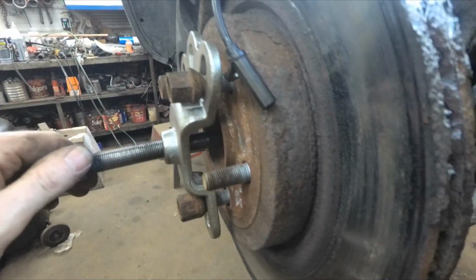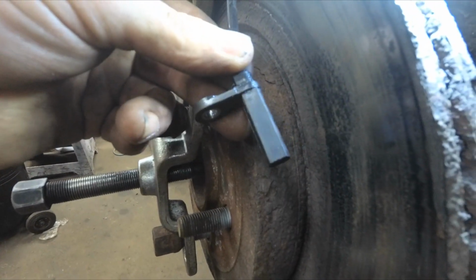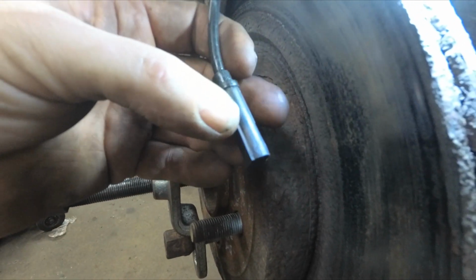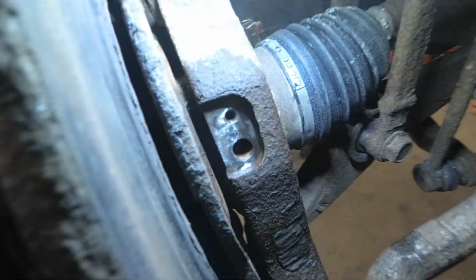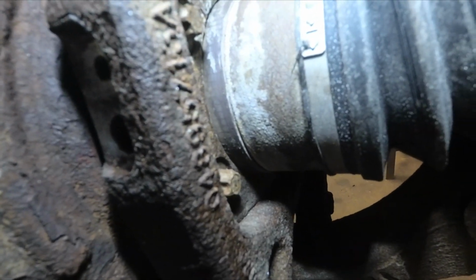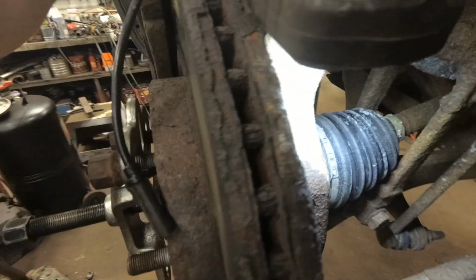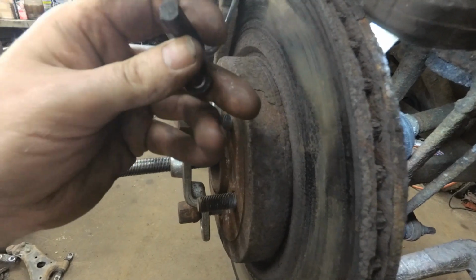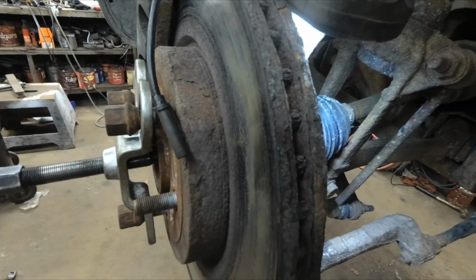So I managed to get that speed sensor out of the knuckle by just using penetrating fluid and wiggling it. It's actually not as bad because it's got these ribs, so it's got room for rust to build up. I've cleaned the mounting hole with a wire brush, and I see that I pushed the axle shaft inboard, and you can actually see the reluctor, and it looks fine. So I pretty much need a wheel speed sensor. Being Sunday, nobody's got one in stock. So we're going to have to wait until we get a new part and put it in and see if that resolves the issue.